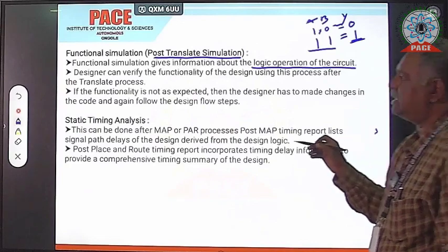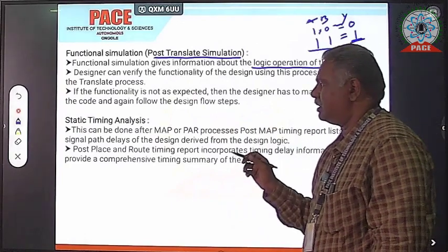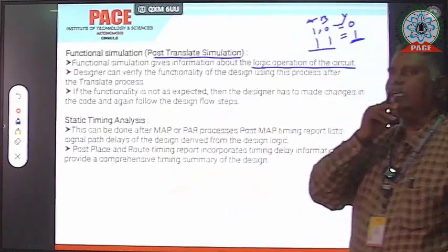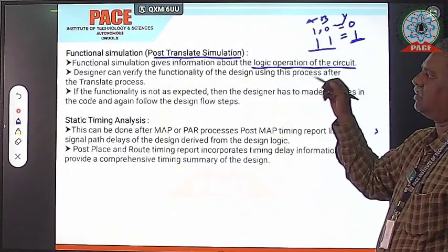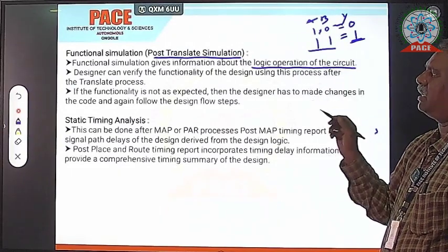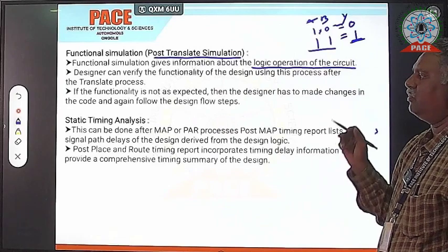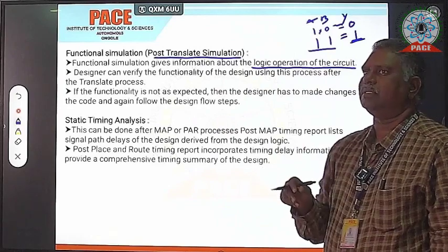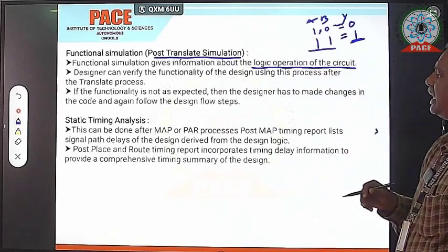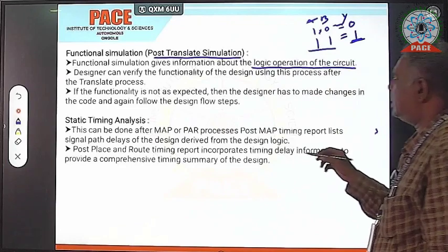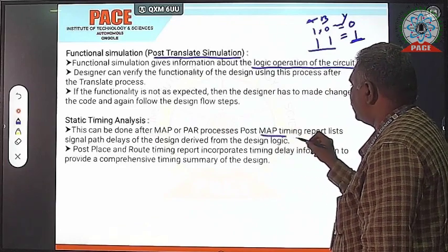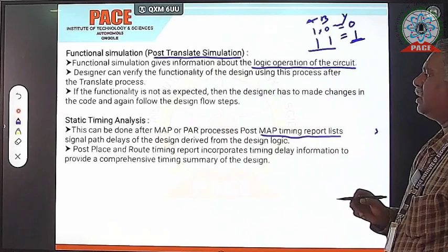After completing the functional simulation, we are going to verify the static timing analysis. So what is meant by static timing analysis? It is a post-mapping timing report, and we need to check the signal path delays.